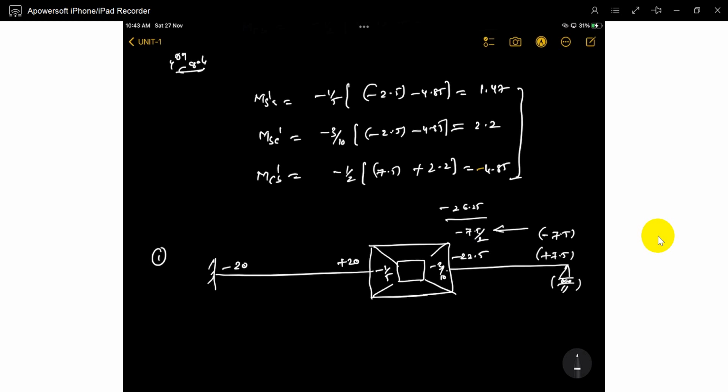That's it, no? So now you can do the problem. You can just eliminate C, the degrees of freedom. You can just eliminate the iteration at the C level. Directly it's plus 20, you can take it as 26.25. You already know the far end receives half of the moment. That's it, no? Just do it. So now it's 6.25.